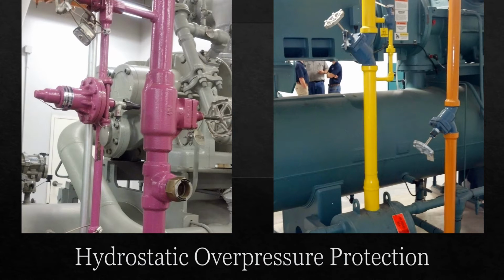Where a liquid can be trapped and cause overpressure due to thermal hydrostatic expansion, overpressure protection must be provided. The images on this slide illustrate 2 different types of hydrostatic relief devices. Standard 9 requires a hydrostatic relief device when liquid can become trapped in any of the following scenarios.